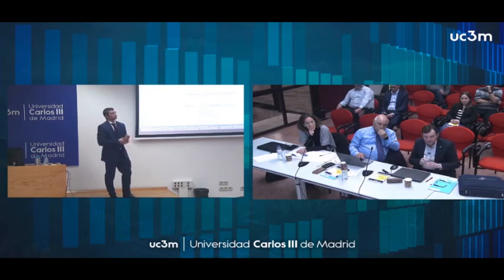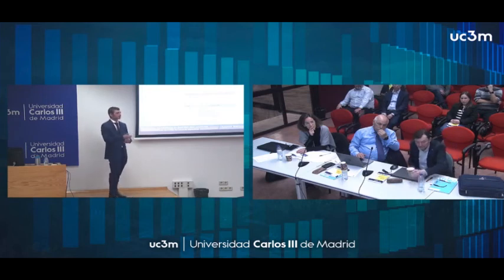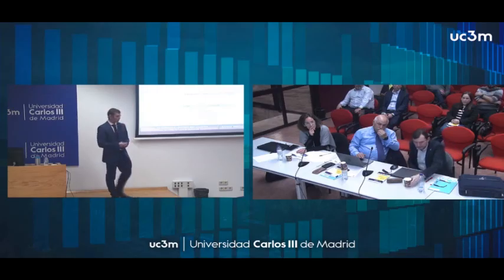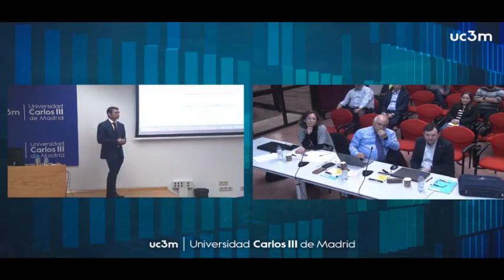So if we were not to design a complete solar field, but to readapt a bigger existing one, we have to take that into account. How wide is it? Where is the focal height located? Where do we obtain the best positioning of the mirrors in terms of concentration, in terms of optical efficiency, sorry, in terms of the costs, because the lower it is, the bigger the structure has to be in terms of width, which also increases the shading. So all of those details, if we were readapting a solar field, have to be taken into account.